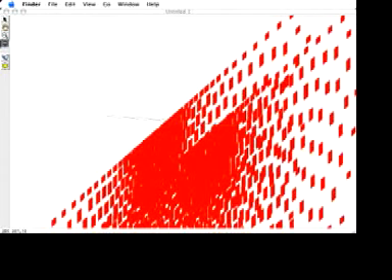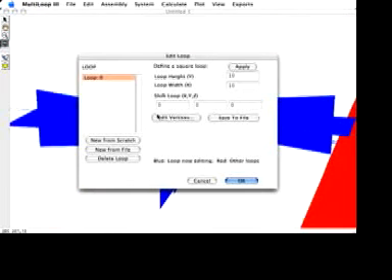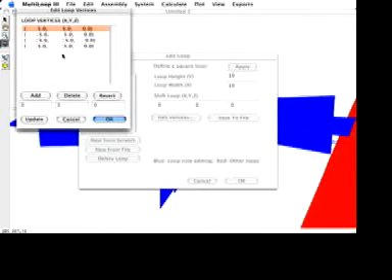In the next part, we're going to add a loop. To add a loop, go to System and select Loops. We're going to create a loop from scratch. Go and edit the vertices. Click Edit Vertices. Here's the Vertex Edit dialog. The boxes on the bottom are the edit boxes for the X, Y, and Z, or North, East, and Z coordinates.